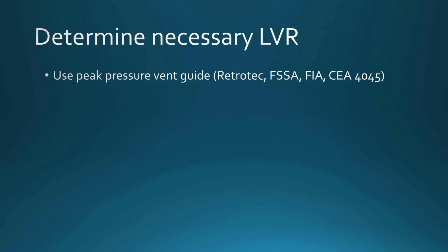the ones that we call the FSSA formulas are the only ones that I believe have been extensively tested. And by extensively tested, I mean tested over a wide range of leakage areas where humidity has been controlled, the leakage area has been properly measured, so we can relate leakage area to enclosure strength. Before, they've measured peak pressures, but they've basically done the same discharge in the same enclosure without really understanding exactly what the leakage of that enclosure was.